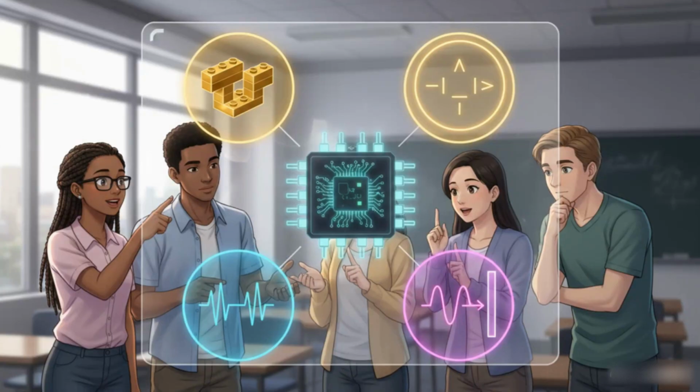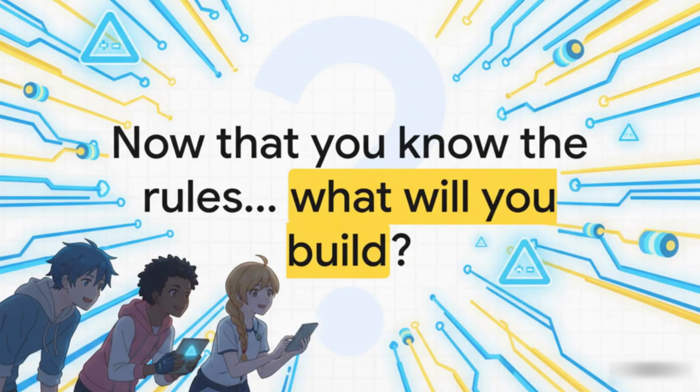So let's pull all this together. The op-amp is our ultimate electronic Lego brick. We use the ideal model to make designing with it super easy. Its two main moves are the inverting and non-inverting setups, where the gain is set by a couple of resistors. But you always have to remember that real-world limits are what define the boundaries of what you can actually pull off. The op-amp is just a perfect example of how a good abstraction can be so powerful. It takes something incredibly complicated, a chip with tons of transistors, and boils it down to a simple, predictable block with just a few golden rules. So the real question is, once you know the rules of the game, what will you build with it?